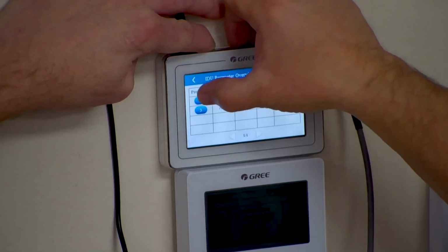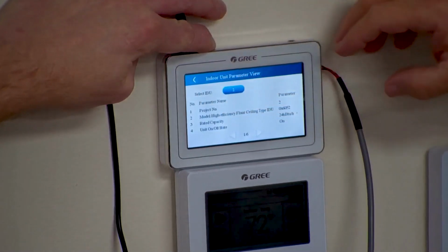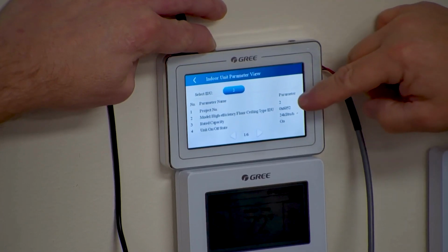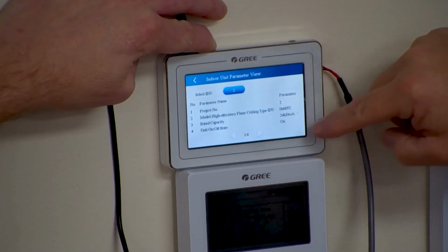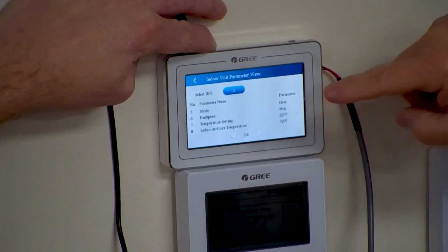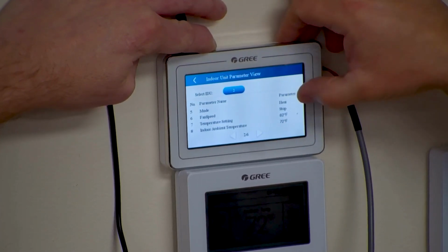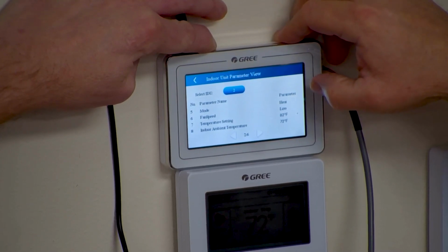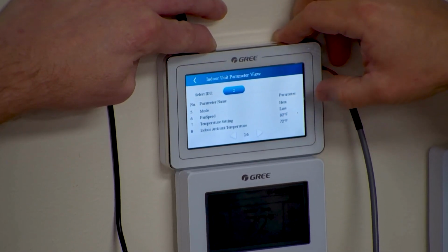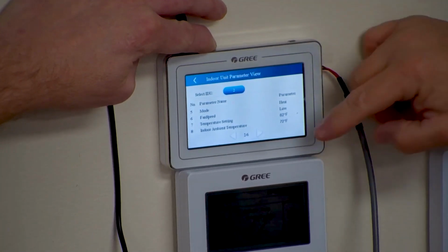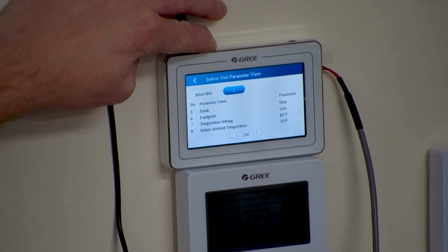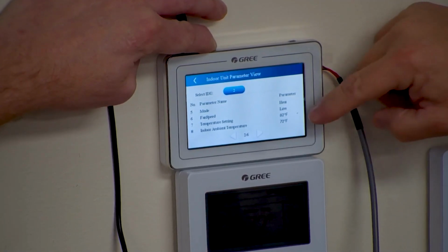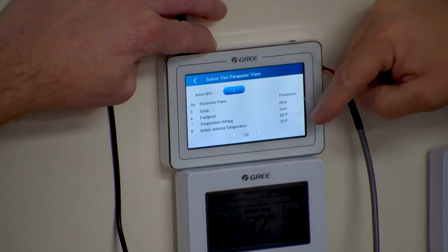Now I can hit that number 2 button, go specifically to that unit. It's telling me that's a 2-ton indoor unit. It's project number 2. The state of running is on. The fan mode is stop, because the way these machines work, the fan's not coming on until the coil's warm. Now it's starting to come on. I think this is the 2-ton, but I ain't going to swear to it because I've got them both coming on anyway. Temperature setting, 82.